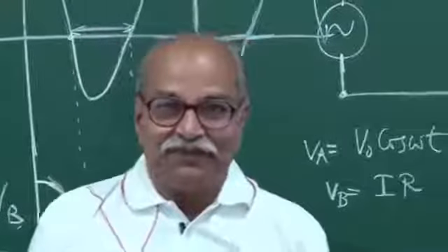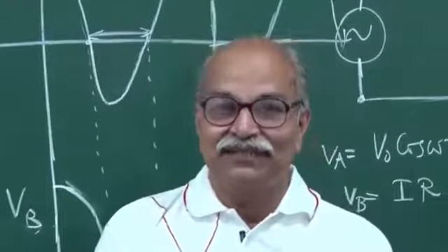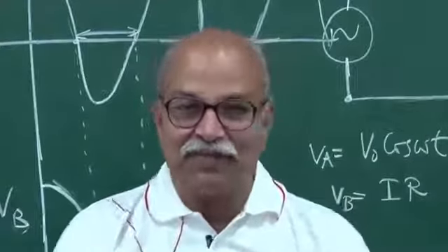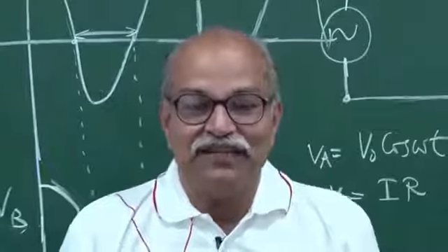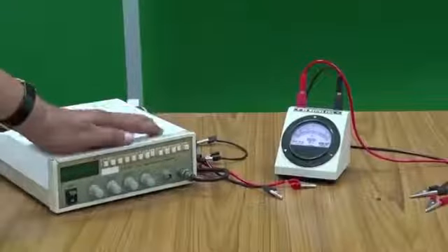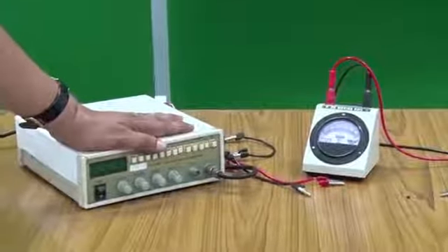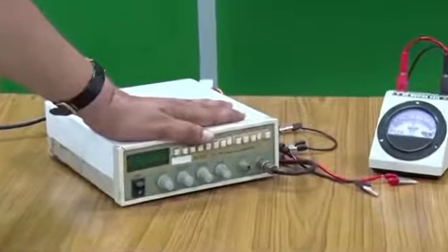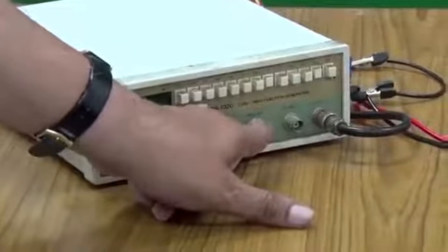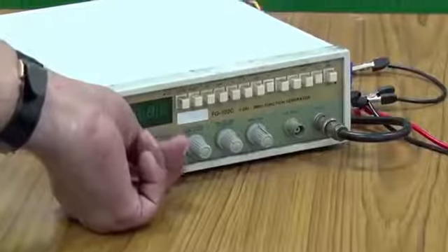Okay, so you can obtain this DC voltage source from AC voltage source just by putting one PN junction in the circuit. So let me do some experiment here to give you some kind of a feel of this phenomena, and then we'll proceed further. So now I have a unit here which is giving me AC voltage, of which I can control the voltage by rotating this knob, the peak voltage, and from here I can also control the frequency of that AC voltage.